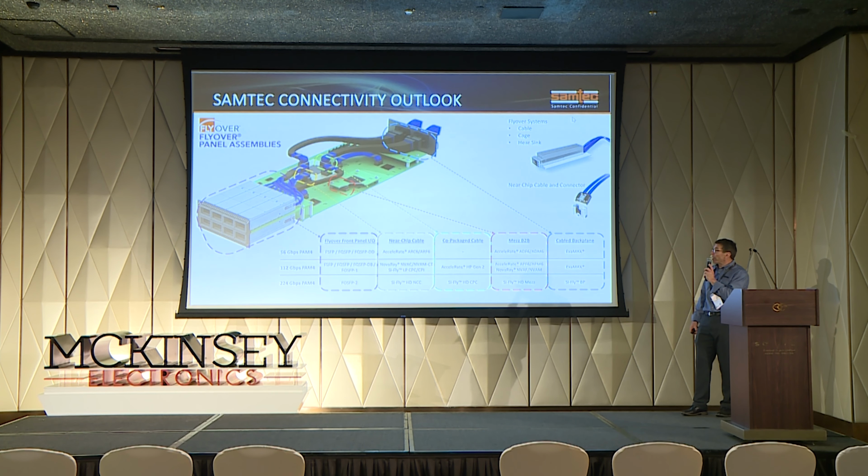It's the connector on package that goes straight out from the substrate into what would be, in this case, the OSFP front panel. So that's taking 16 twin-ax cables at up to 224 gig data rates straight from the package. We also do near-package designs where you're taking your signals out of the package, into the BGA, across a bit of PCB, straight into connector, out. It's all about streamlining your SI performance for reach and channel performance and bit errors.